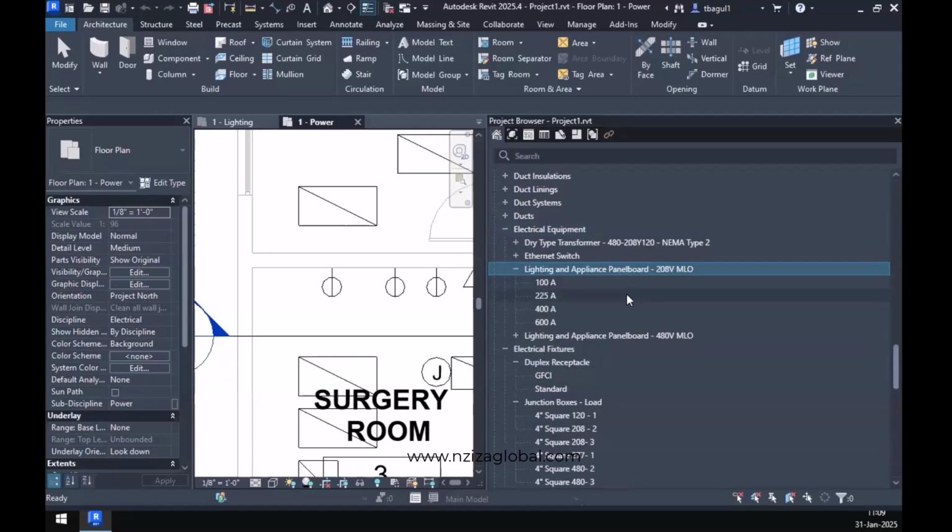Now, based on the loads that you will be calculating, you want me to show this one more time? Okay, I'll take that as a no. But what we need to do is have the conductor properly designed for our panel board. This is dependent on the demand load calculations that we spoke about yesterday. Connected load into diversity will give us the demand load. That will be in VA or kVA. Divide that by the voltage and it will give you the amperes.